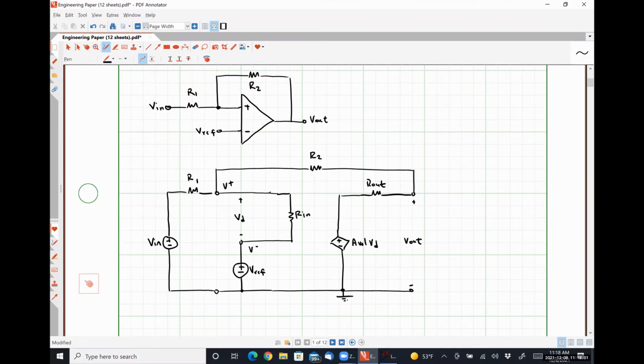You just assume that's connected to the positive terminal of V out. So this V out terminal is the output voltage measured with respect to ground. So it has to be connected to the positive polarity terminal because the output is measured with respect to ground. If it was connected to the negative polarity terminal, V out would always be 0. All right, so is how I redrew this circuit okay? Anybody got any questions, comments, or concerns?